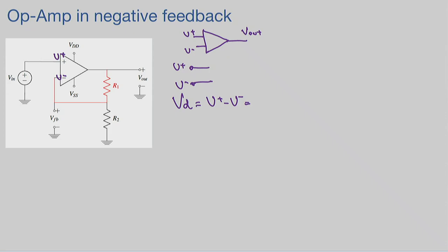Okay, now we know that in our models there is a current. We could say there is a current going here, which we would call I in. And what is that current? What's the current going into the op amp? What's the current? 0. You can say 0 because it's an open circuit.